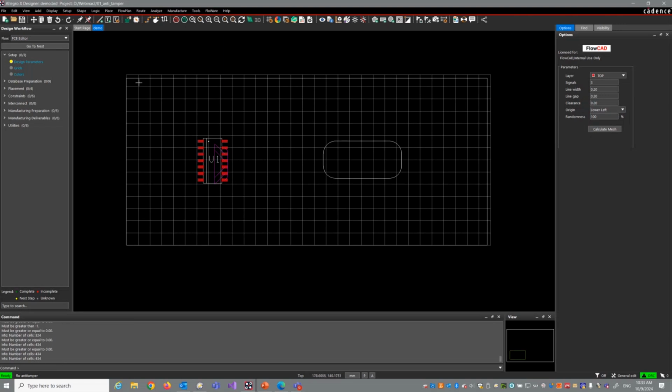And of course, it's quite obvious. Whenever we generate some traces, each cell which covers a design outline, which covers any keep-out or cut-out, or which touches any edge-related objects within a given distance, has to be disabled by default. You can do that manually. You can say, clear cells manually. But this is time-consuming. So rather than this, we use a check region overlap. That means everything that is intersecting with a selected region will be disabled automatically.